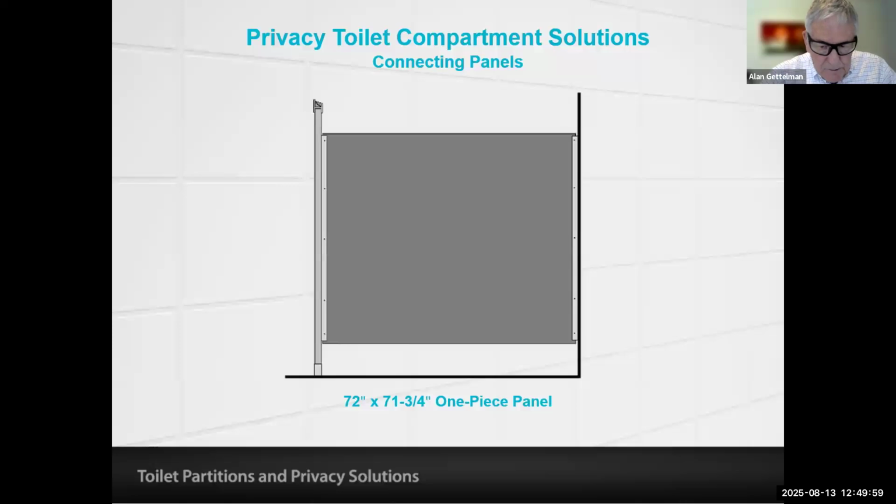ADA accessibility standards specify 9 inches minimum toe clearance above the floor under the front and partition and one side of wheelchair accessible compartments. To provide toilet compartments with toe clearance below the 9 inches, compartments must be designed to be 62 inches deep minimum with wall hung toilets, and 65 inches deep minimum with a floor mounted toilet, and 66 inches wide minimum.